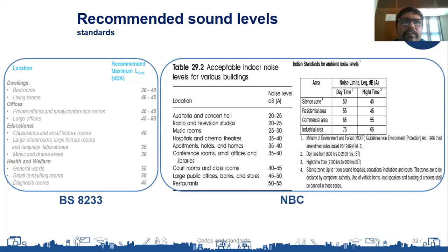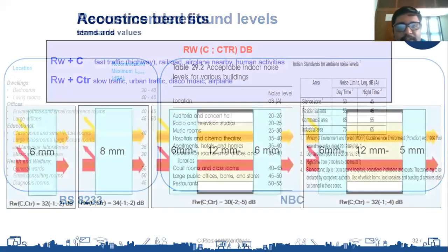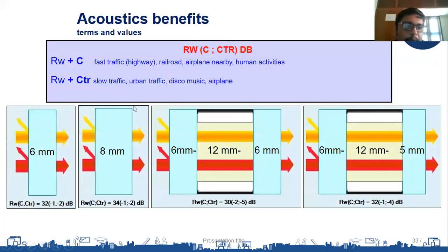Today we have a lot of acoustic consultants who do this analysis, who measure the different frequencies of noise outside and the noise level outside, and by that we know how much noise level is to be maintained inside. Based on that, we can calculate what is the noise level to be reduced by the glass. When you arrive at that, glass manufacturers usually give these reports: Rw, C and Ctr. Rw is your weighted average noise reduction factor. C is your high frequency correction factor. Ctr is your low frequency correction factor. I'll give some background to this. I'll just spend a few minutes on the slide.